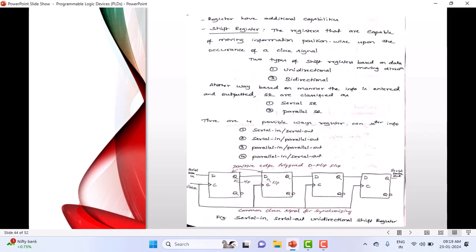If it is a falling edge, what will happen? When the falling edge comes here, the state of the flip flop will change. That means this flip flop will ignore the rising edges if it is a falling edge. Understand the difference? It all depends on what kind of registers you are designing. You want rising edge, these are the flip flop registers here. If you want falling edge, you can also do that.